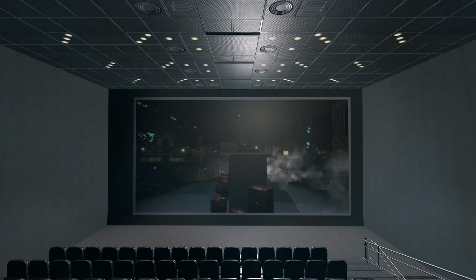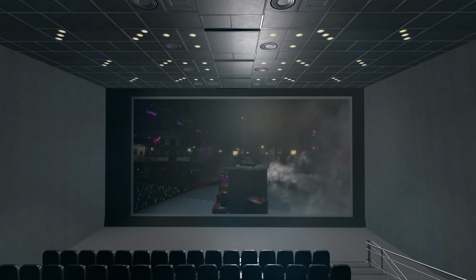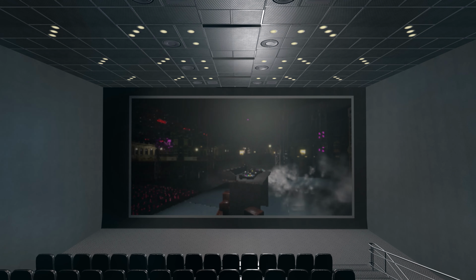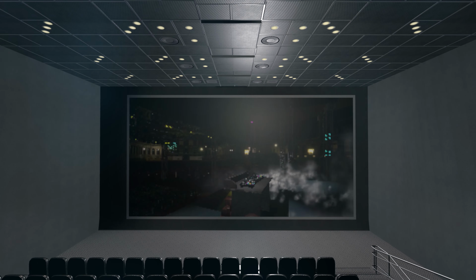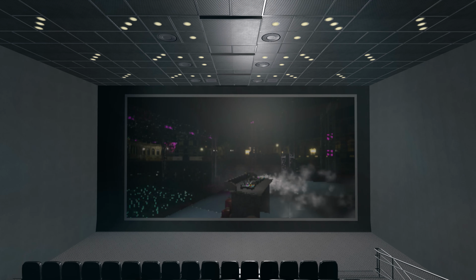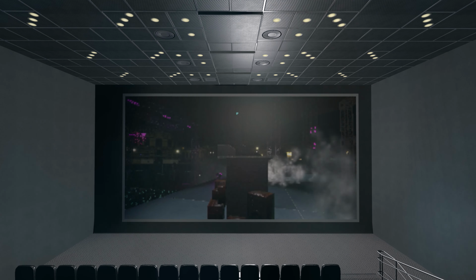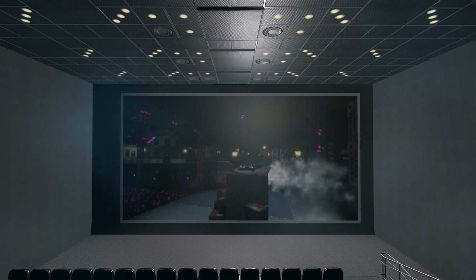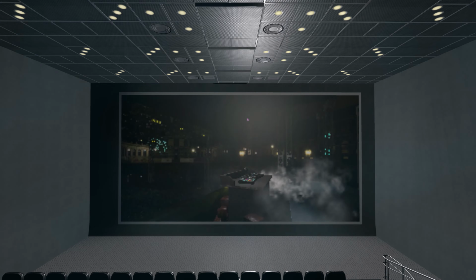The surround speaker channels are set individually to minus 3 dB compared to the master channels because the acoustical sum of both surround channels adds up to 0 dB if the content is equal. Surround speakers must provide uniform coverage of all the audience. Here the spacing between speakers, height above floor, and aiming angle are important. The sidewalls should not be reflective, to avoid any kind of flutter or side slap echoes. The walls must be acoustically treated with absorptive material down to a height below the ear height of the seated audience.